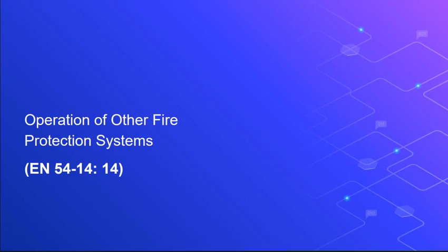All kinds of control and command operations that can be done by the control system and security system related to the devices by other systems such as building automation systems must in no way prevent the emergency control operations to be made from the fire control panel in case of fire or a similar emergency.